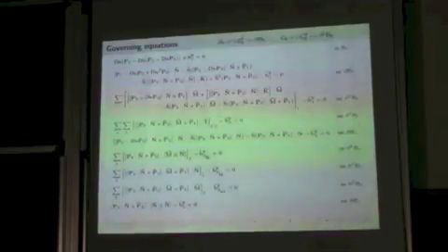Now, I have to have this slide with many equations. If you remember, we had basically 9 types of integrals, so that gives us 9 equations. And of these 9 equations, the first one should be familiar to everybody. This is just the divergence of P1 minus divergence of P2, the second pure stress, and P3 was the third one. So this is pretty much what you have in the bulk for the third order continua. The second one is on the surface.